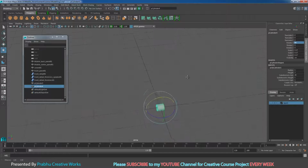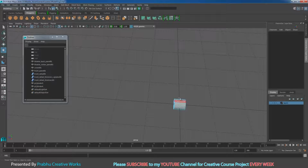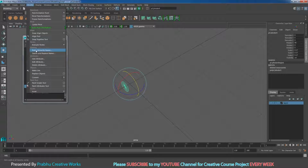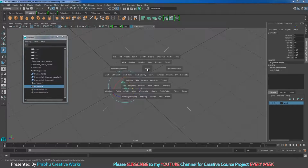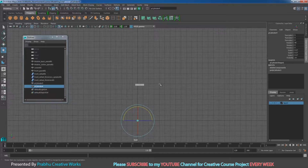So right click on this object and choose face. So I will select this face and delete on the keyboard. So right click and choose object mode. So I will select this object, go to modify and choose center pivot. Center pivot, go to front view, press 4 on the keyboard.